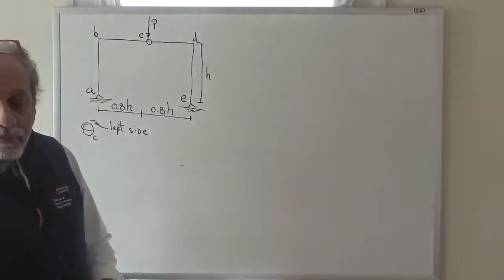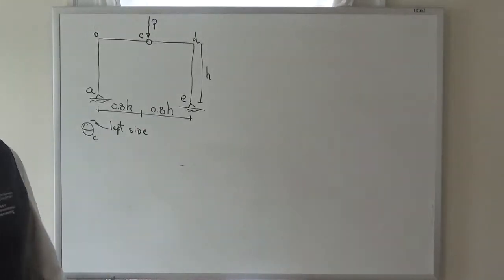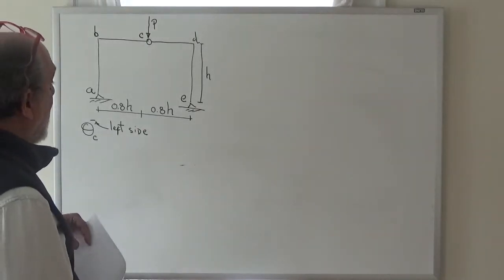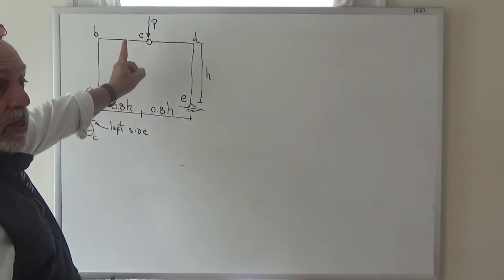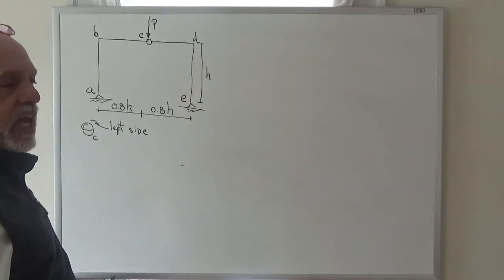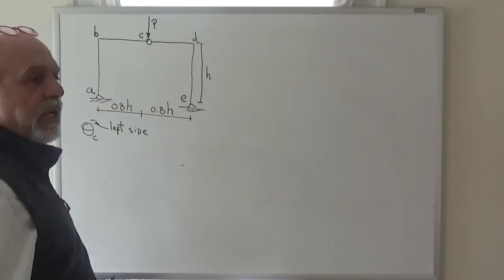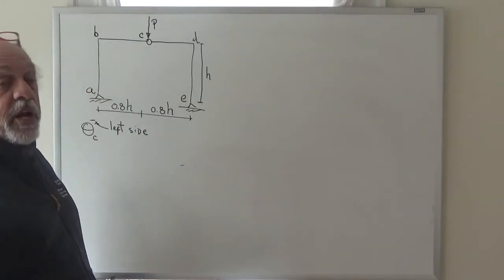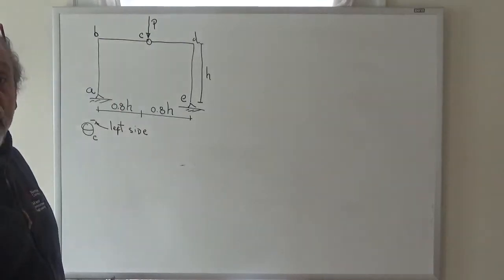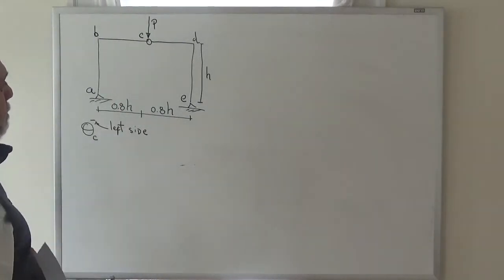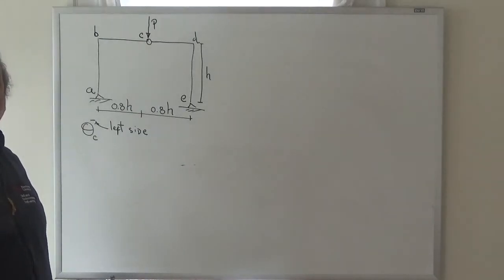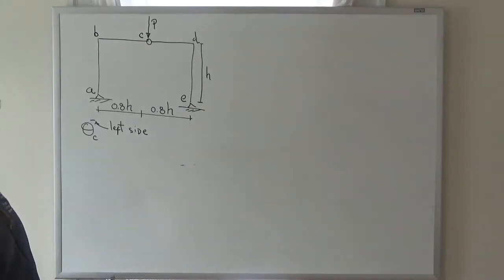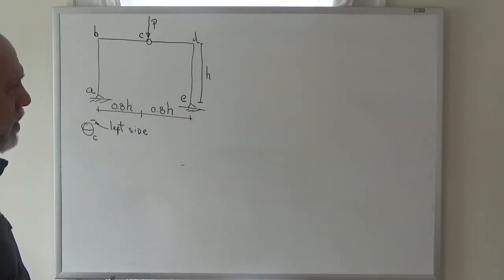And of course, to me it's obvious, but I hope that to you it would also make some sense, that if you were to move that load 1/1000th of a millimeter in one direction or another, so that you're on one side or the other side of the hinge, you don't expect that this structure can actually know that you've done anything, since the load is basically in the same place. Okay? The issue of whether the load is on the right side or the left side of the hinge becomes important, or can be a confusion issue, when you make free body diagrams, because you can wonder, is my load here or is it not, and so on.